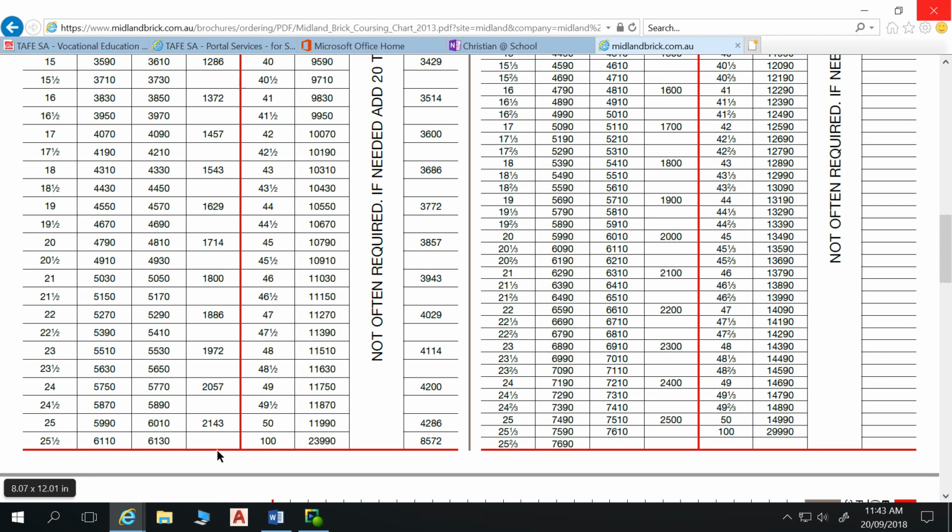And working back to your carpets, even if you get carpets on the floor, will be 3600 as well. So that's sort of the maximum size I think a domestic bedroom or room is going to be. So all these increments of 300 millimeters. You'll see these increments of 300 millimeters popping up in buildings all the time. That relates back to your standard bricks.